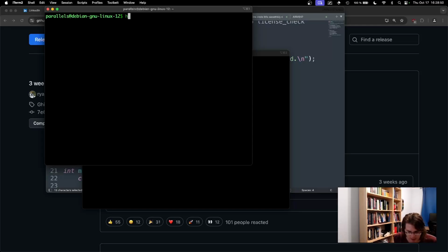easy way. So since it's hard-coded, and especially in the embedded security area, we see a lot of things which get hard-coded, like cryptographic keys, hard-coded passwords, and so on, licenses. So we see in the embedded world a lot of things are hard-coded in binaries. And these can be similarly dumped as we do it now. So if we do the hex dump of the license check again,